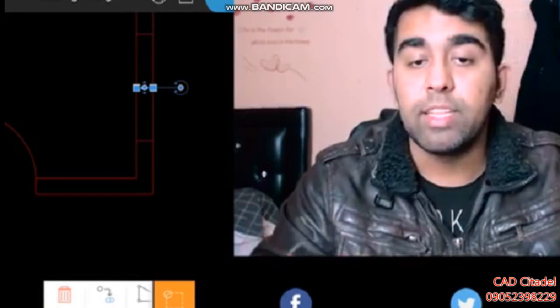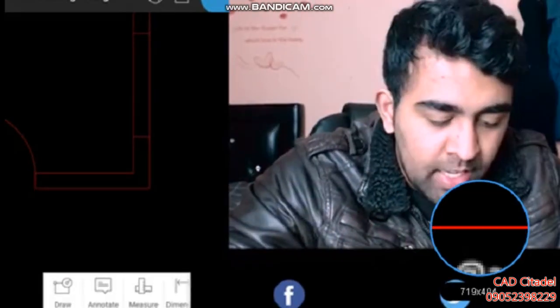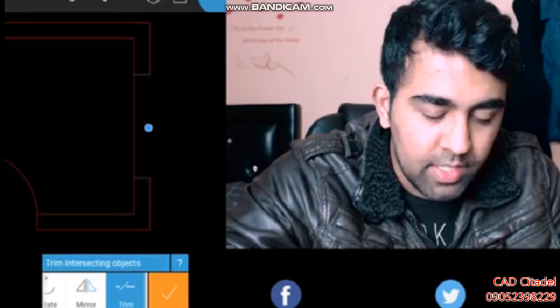Okay, and then we're going to change this to, let's say, 2 feet. Okay, so let's deselect everything by pressing on this yellow button, and then I'm going to get rid of this middle line. So select that, go to your modify panel. It automatically takes you to the modify panel here. So let's delete that line now, and now we're going to use the trim command. Okay, so let me select this line and this line, and then select that trim command, then get rid of this, right?